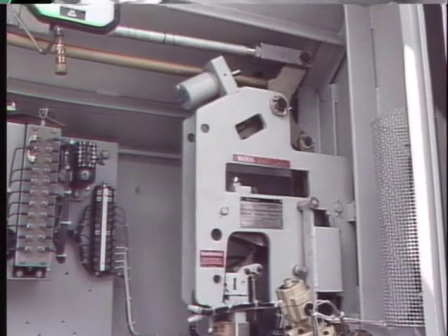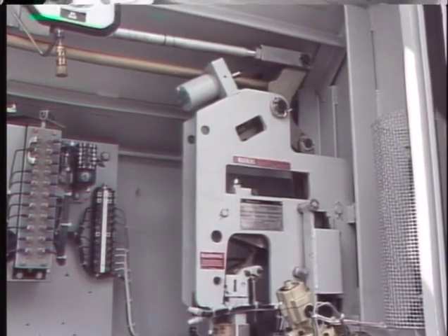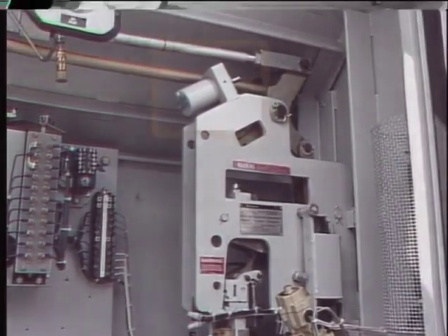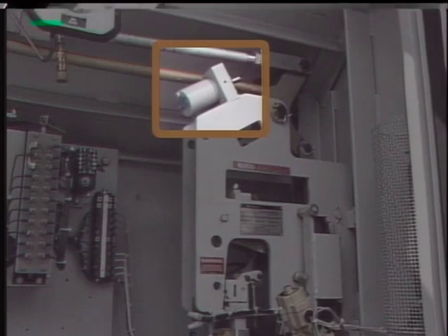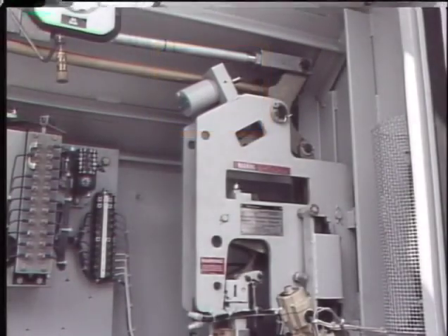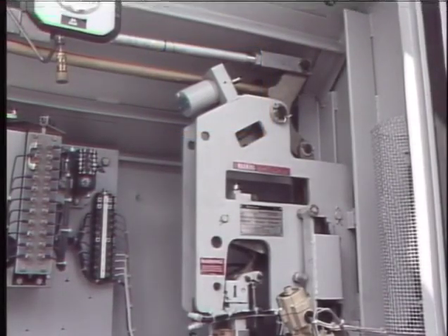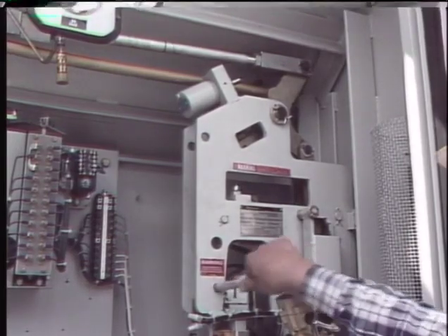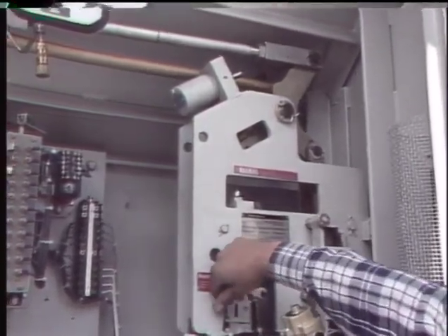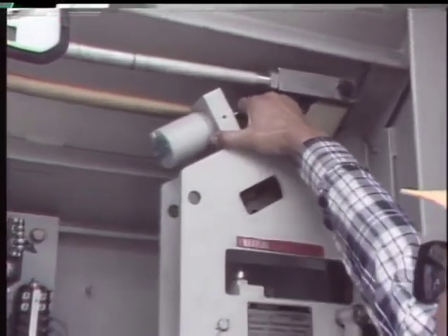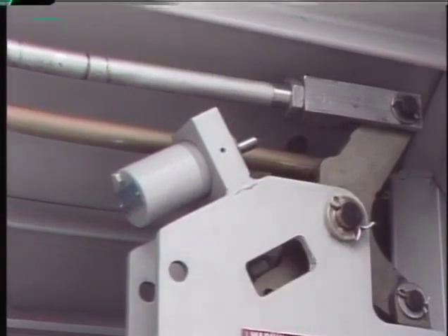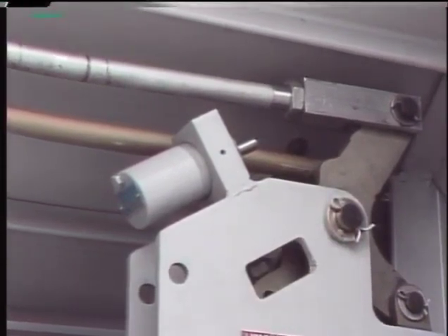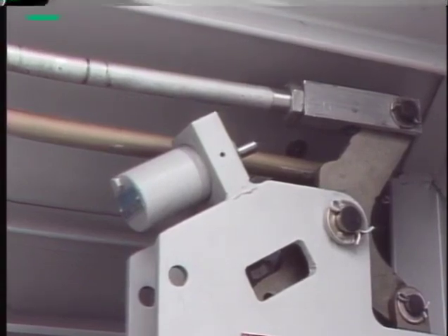One common operating mechanism that is usually checked with the breaker partially closed is a shock absorber, often called a dash pot. Dash pots cushion the impact of rapidly moving mechanisms, primarily when the breaker opens. With the breaker closed, the mechanism linkage is lifted off the dash pot. The dash pot is moved by hand to see if it moves freely. If it doesn't move freely, it may not properly cushion the mechanisms when the breaker opens, and the mechanisms could be damaged. A stiff or jammed dash pot should be fixed or replaced.